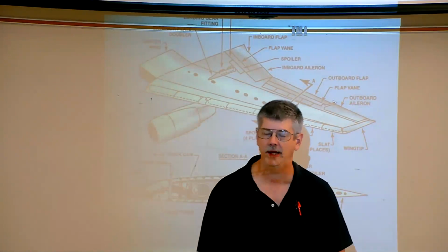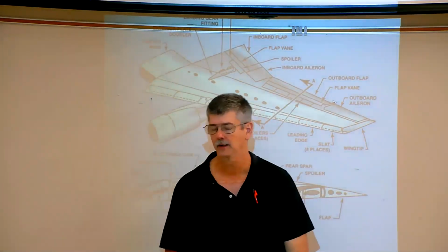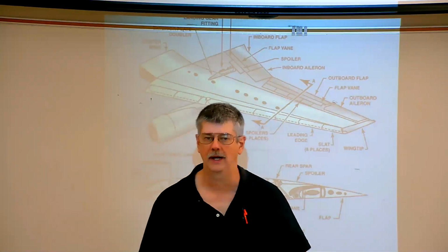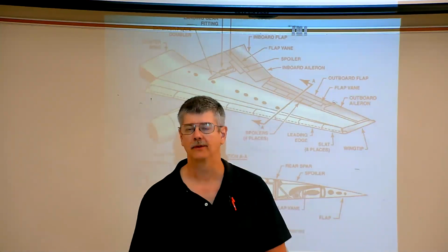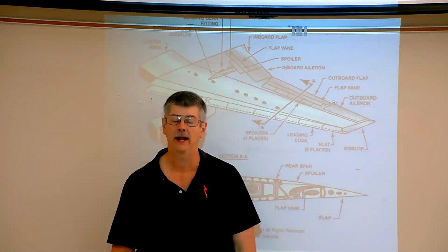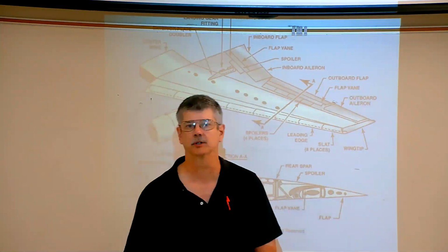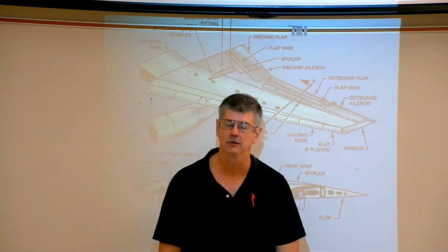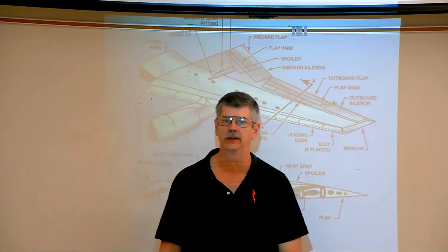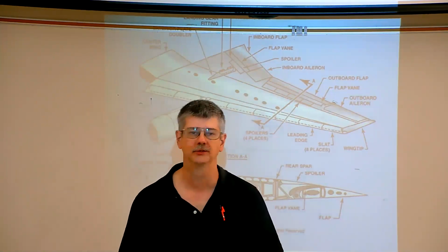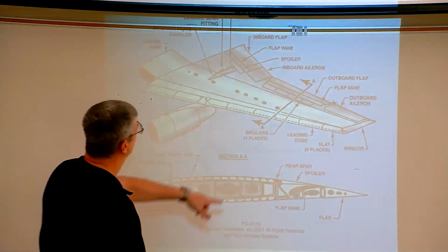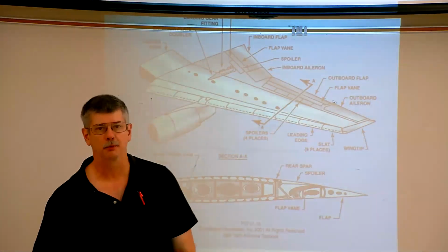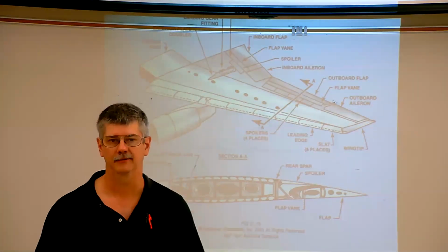During slow flight or when the flaps are extended, depending upon the aircraft, both ailerons will operate together. When the flaps are retracted and or the aircraft reaches a certain given speed, then the outboard ailerons are locked into the neutral position, and only the high speed or inboard ailerons will function, okay? We talked about the trailing edge flaps, and then we have the spoilers. The spoilers are there to reduce lift.